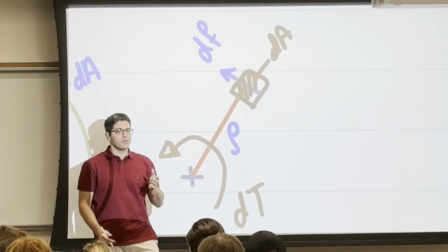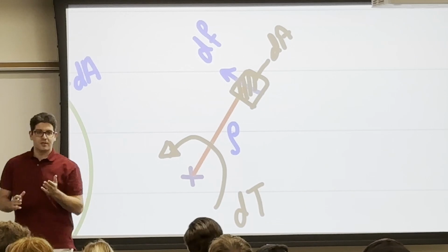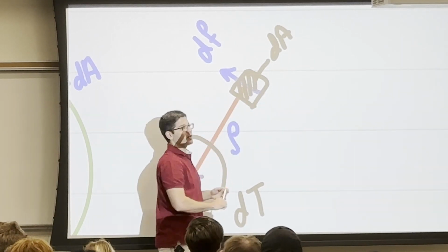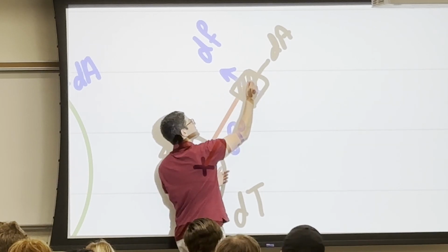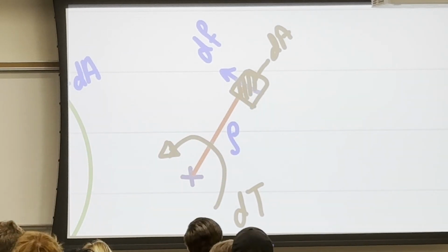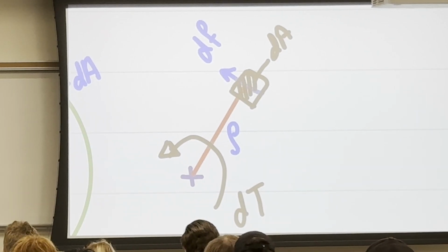Force over area. But now you need to tell me, is this a normal stress or shear stress? Shear. Because the force here is parallel to that area, right? If I did have a dF that's coming in and out, that's when we will have a normal stress. All the stresses share the same thing, force over area, but you need to know what the output is.